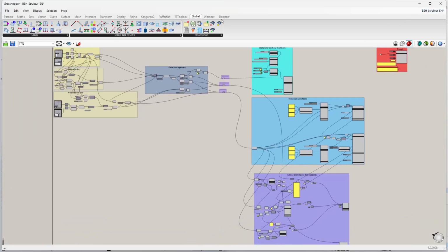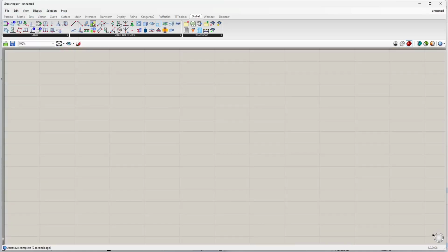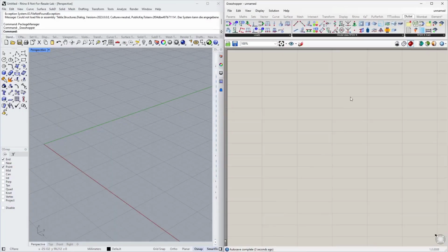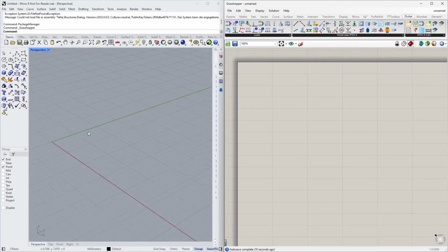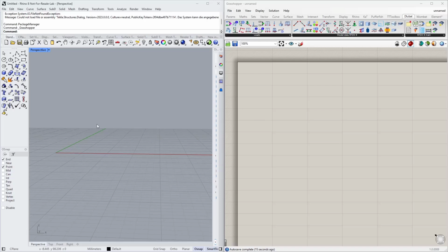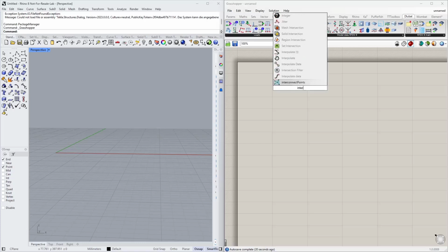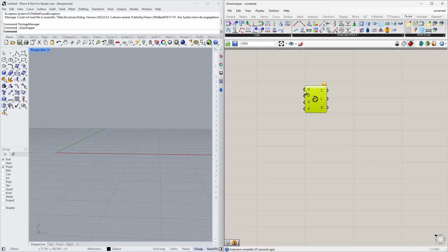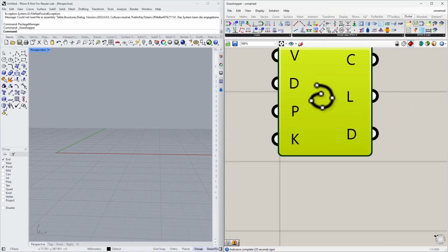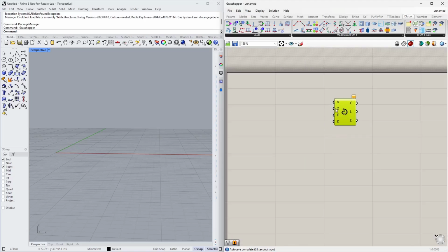All right, so let's create a new file in Grasshopper, move it to the right hand side of the screen and start with the modeling. As I said, I would like to begin with the Grasshopper algorithm. So I need a plan how to model that, and I will start with the roof. The roof was curved, and therefore I need a curve with the interpolate component. The interpolate component requires the nodes. You can see it basically on this little icon here. You need to define the nodes and then it will interpolate a line or a curve.